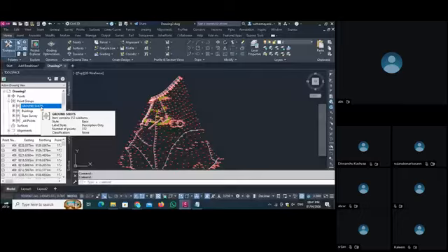So in today's exercise for the point groups, you have to create all these point groups. I will provide you all the source names which are provided in our file. As per those names, you have to create all those codes first, if you don't have any codes in your Civil 3D, and then you create your own groups.